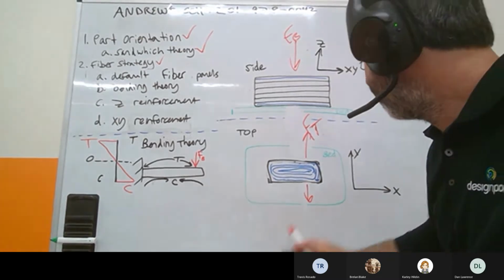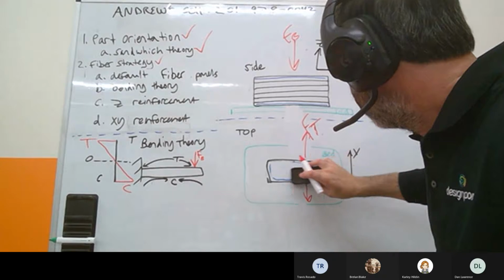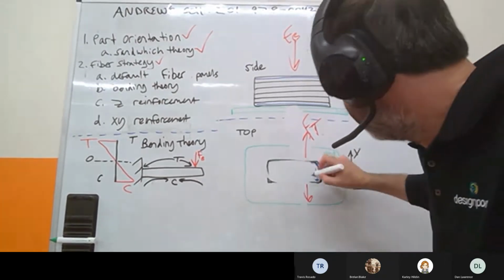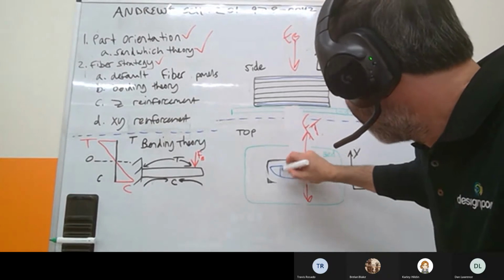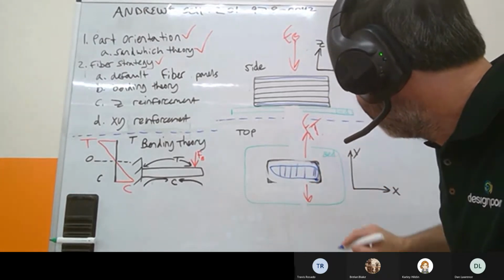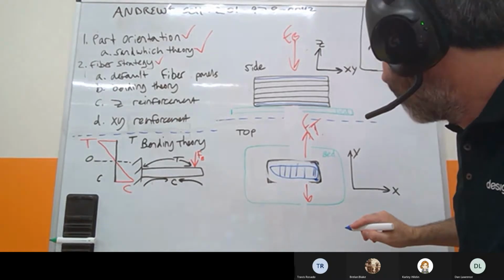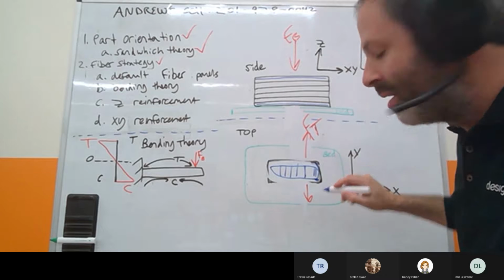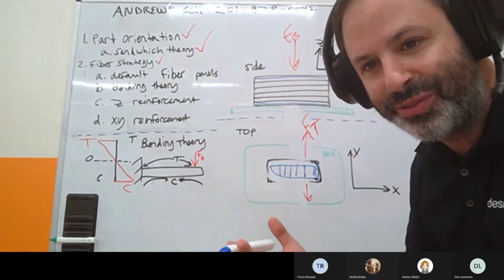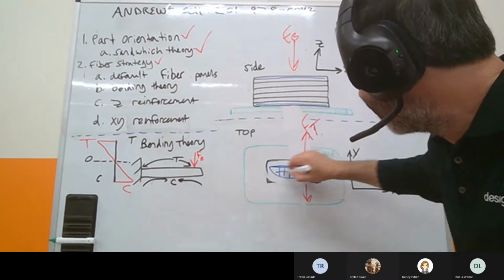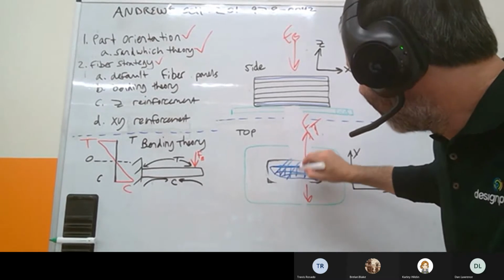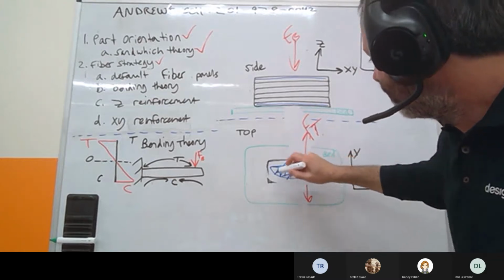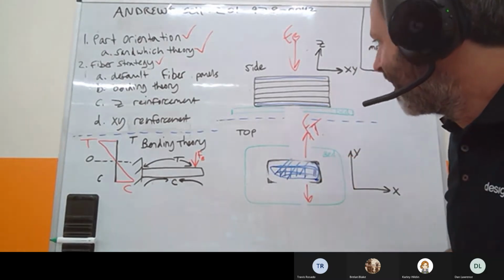Because think about it, if you use the isotropic fiber, when it goes this way, that's really great, because you're putting the fiber into perfect tension. But we said each layer goes a different direction, right? So the other layers aren't going to be as good. So that's why it's better to just actually use a concentric load for that instead.